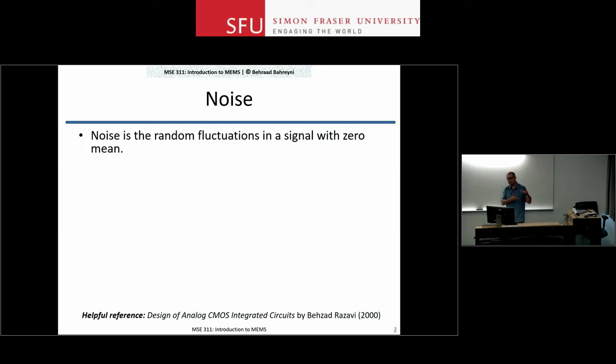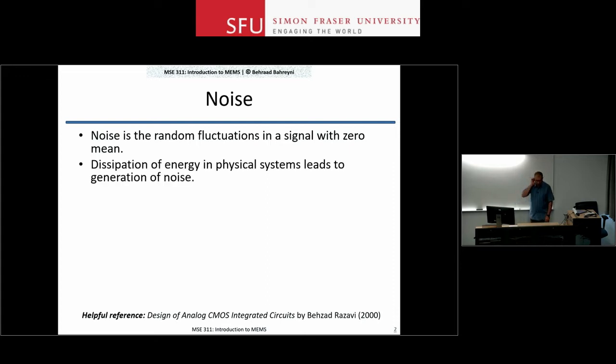So something becomes softer over time, or a mechanical joint becomes harder over time or stiffer over time, and it's not changing randomly. So that again is not noise. For a signal to be considered noise, it has to be random and it has to have a zero mean, meaning that if I integrate it over a long period of time, all those random changes should cancel out.